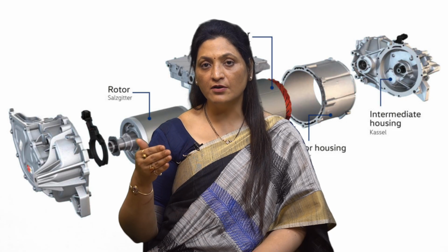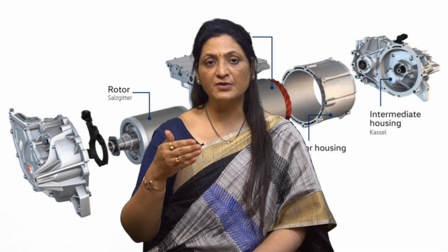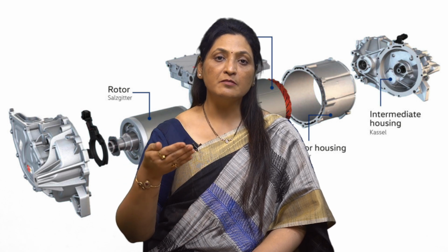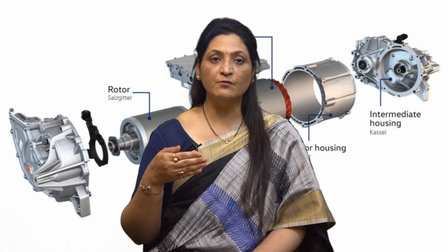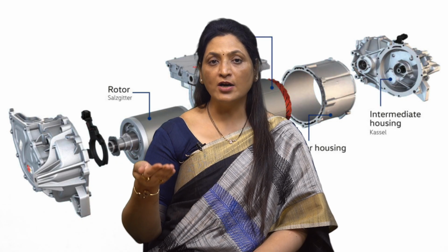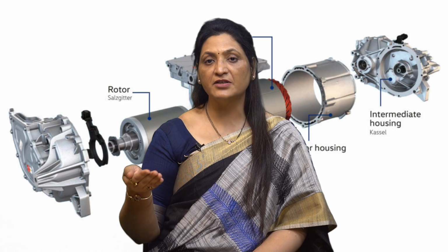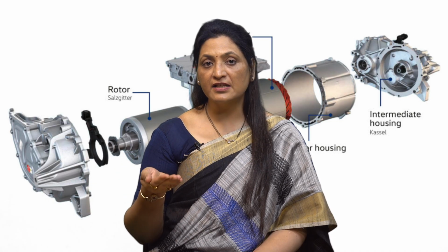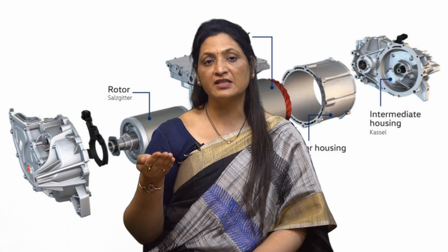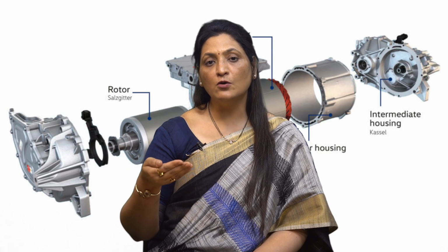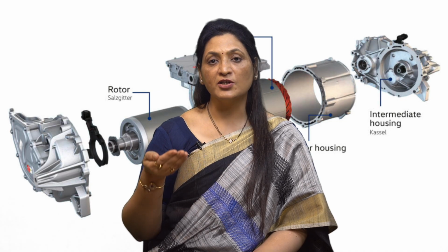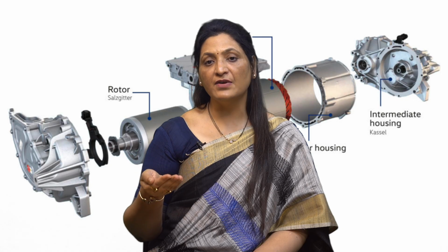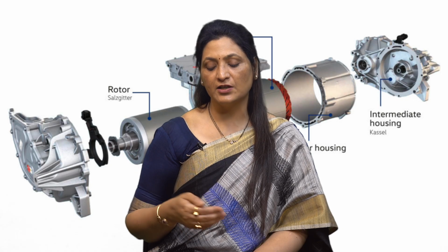continuous and constant load, for example, in centrifugal pumps operating under the same condition for a long time. Continuous but variable loads, examples hoisting winches, conveyors, etc. Short time intermittent loads, examples excavators, cranes and hoists. Then we have pulsating loads such as in reciprocating pumps and textile looms. Then we have impact loads such as in rolling mills, forging hammers, shearing machines, etc. Such machines have flywheels attached with them for load equalization.